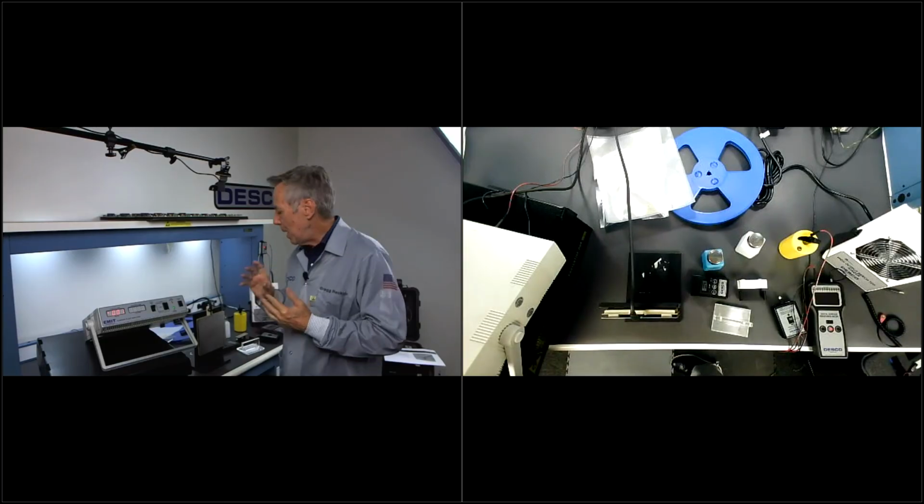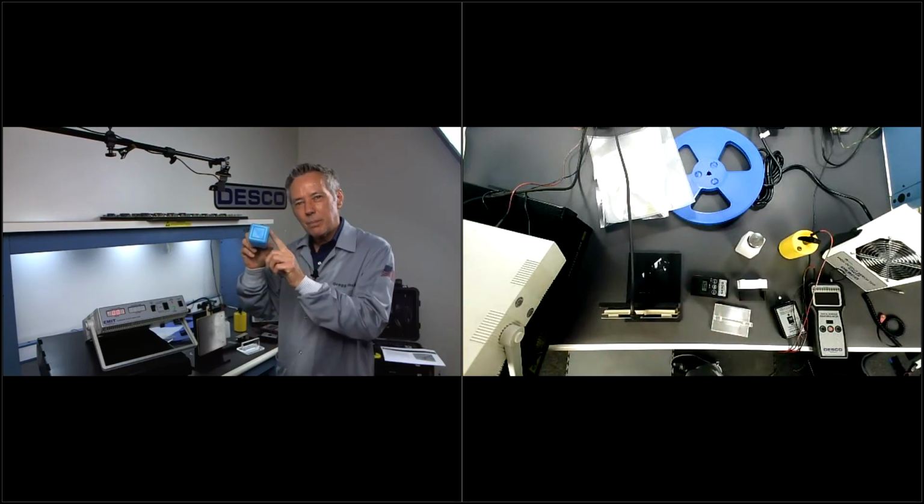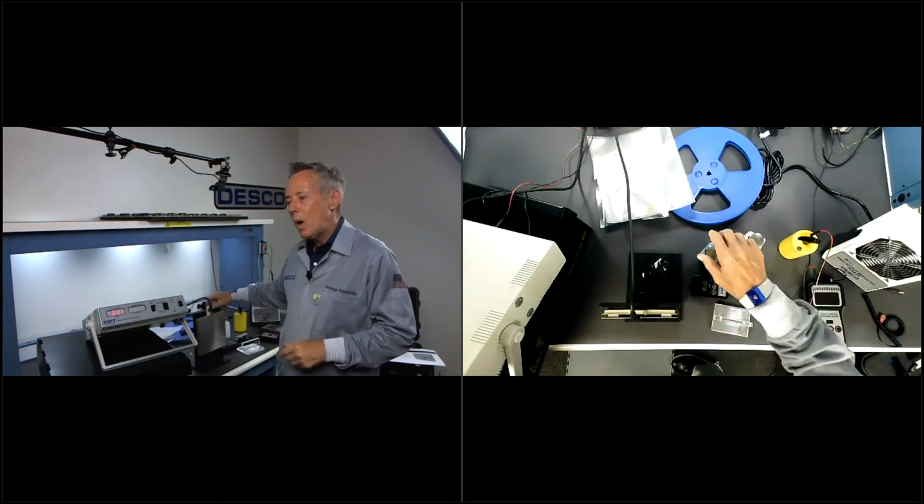And so those are pretty much the basics of ESD. We can get more in depth later. If you want to contact us, I'll put up my contact information. But we're talking about, again, grounding all conductors, removing insulators that we can, and if we can't, we want to either buy that thing we need to be protective, ESD safe, or we want to neutralize it with ionization.